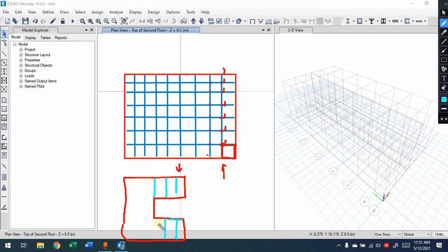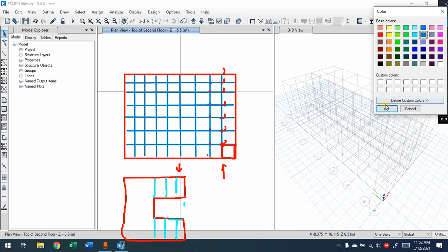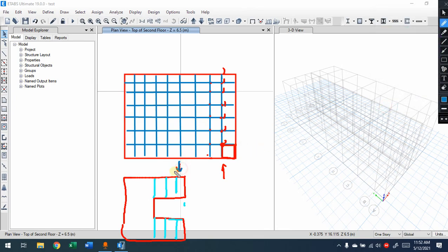If you apply semi-rigid here, it means that this part can bend like this. So if I represent some deflection of this shape, let's say applying load here, what will happen? It might happen like this, but this one will not move if it's semi-rigid because they are not linked directly. If you assume rigid diaphragm and apply load here, even though there is a space here, because you applied fully rigid, the other part as well will be bent like this.